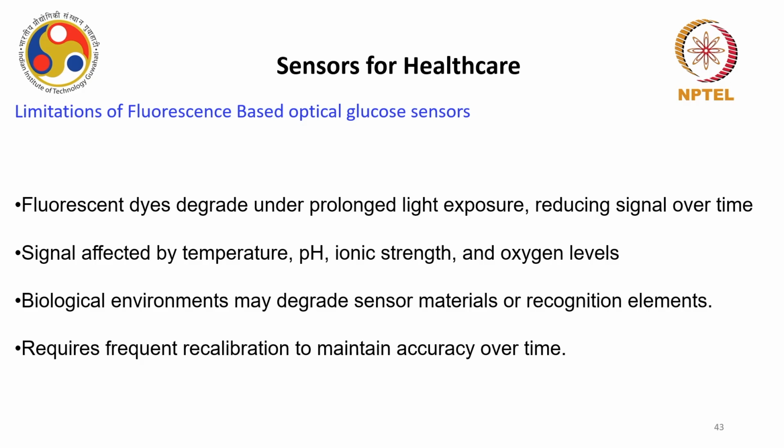Okay, the biological environment can degrade sensor materials or the recognition element. They require frequent recalibration to maintain accuracy, and this requirement is continuous over time. Meaning you should not think that you have a fluorescent sensor, you have calibrated it once and it will not require more; it will keep on demanding the calibration.